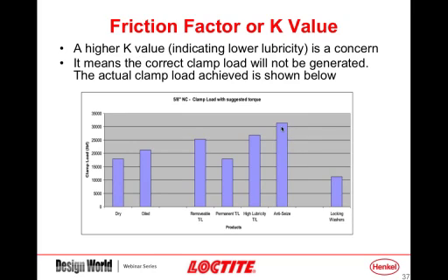So you get your highest clamp load with an anti-seize. If you are using that same unadjusted torque value, you're generating much lower clamp load with the mechanical fastener. And this would be the concern that from the start you have not achieved your design clamp load for the system. So it is important to make sure that your torque specs are set so that they accommodate the thread locking system that you are using, whether it's mechanical or liquid.